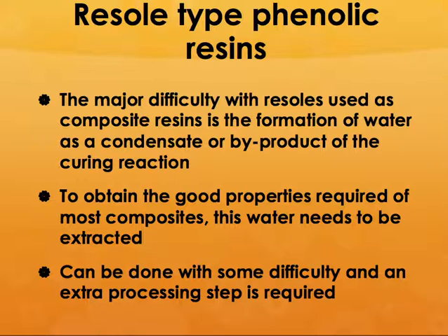The major problem with the phenolic resins in general is that there is a byproduct that is caused as water, and if you are careful, you can remove the water very easily, but most often, if your component thickness is greater than, say, 1/8 of an inch thick or 1/2 of an inch thick, the amount of steam and water that is held between the prepreg or between the fabric layers is going to be difficult to be removed.